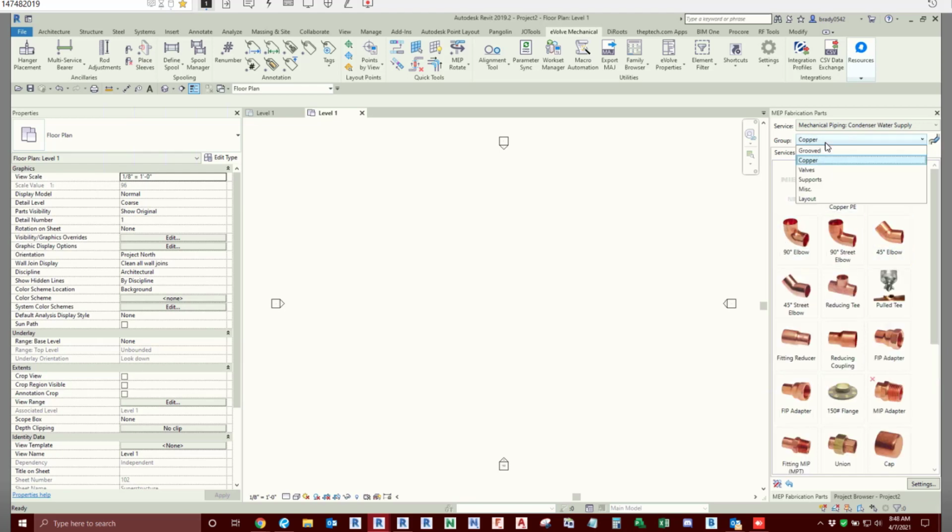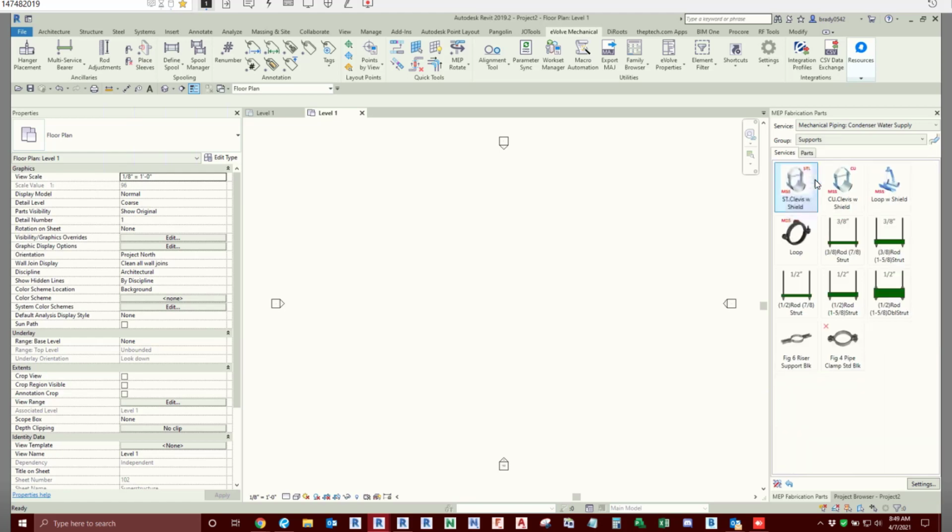The hanging requirements are different, even by size on the piping side. I know that the sheet metal guys, we like to standardize our distances, and that's awesome. The piping guys, it's a little more complicated. But what's real important to understand is that for each service, and this is again why we don't have our standard set up yet, you will have different hangers in the palette depending on what material you have and what the hanger specification is on plumbing piping specifically.